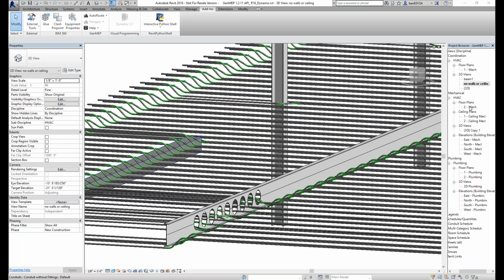So Hare with Whiting Turner asks, what are the families that are within or outside Revit that cannot be recognized by this feature? That's a pretty broad question. Right now, what we do is when we programmatically look at a start or a stub, we go through and determine what type of system it is based on the information in Revit, and then we route. So we have to be able to discriminate between what is a conduit, what is a pipe, and what is a duct.